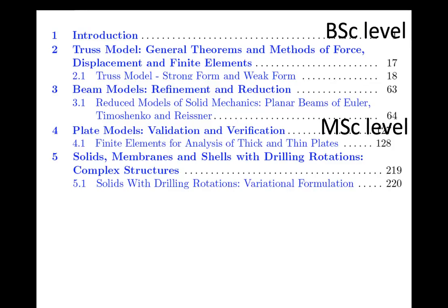And then what's verification? Typically, the problem we want to solve is too complex to be solved analytically, so we solve it numerically. And basically, you're talking about the density of the mesh, whether you actually have enough elements to get sufficient accuracy of your computation. This has been illustrated for plate theory, where instead of Euler-Bernoulli we talk about the Kirchhoff-Love plate, and instead of the Timoshenko beam, the Reissner-Mindlin plate. One is thin, the other one is thick. Thin means you don't include shear deformation, thick means you do. So validation becomes simply, in this illustration, whether shear deformation is included or not.